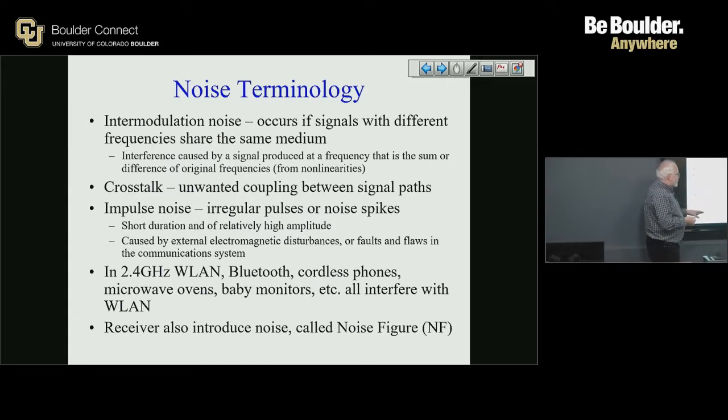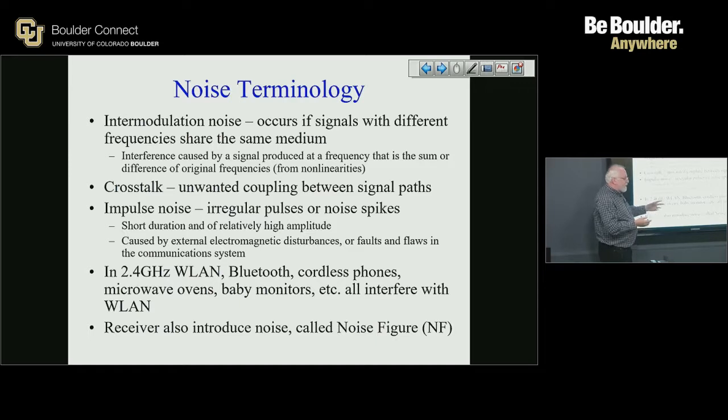The final thing to note here, and this is most relevant in radio telescopes especially, is when the antenna is coupled into the front end of the whole receiver chain. It's called a low noise amplifier. So as I mentioned the other day, this can be femtowatts of power. So we've got to get that boosted up by several orders of magnitude to get it into the receiver processing system. That first amplifier is very critical, the noise figure of that. So it's pretty typical for Wi-Fi systems to have an additional 3 to 5 dB of noise added to the signal as it boosts it up in that initial low noise amplifier.